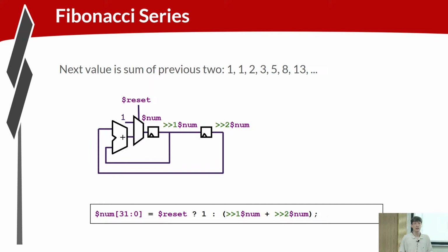So the organization of your logic into pipelines is more to match your thought process, right? Say you've got a design with 7 different pipelines. You could take all that logic and stick it all in the same pipeline. All of the logic that's naturally flowing through a pipeline is going to look very natural in the code. Anywhere that you need to reference across pipelines, the references are going to explicitly reach across the pipelines, so it stands out that you're communicating between the pipelines, which is a good thing. You want the natural things to look clean and the unnatural things to stand out.